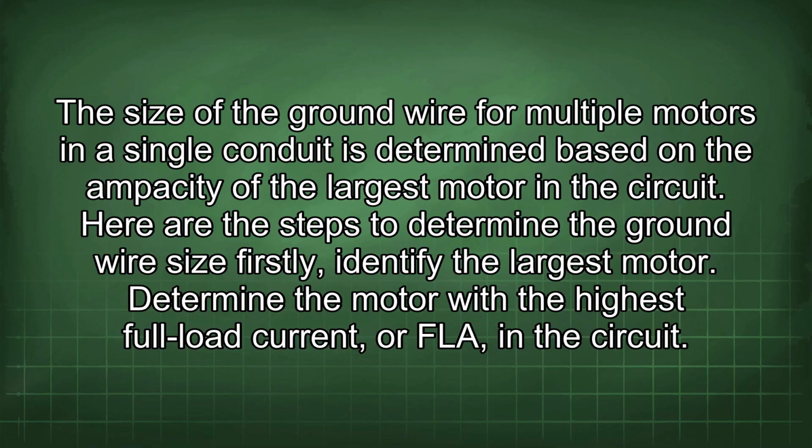Firstly, identify the largest motor. Determine the motor with the highest full load current, or FLA, in the circuit.